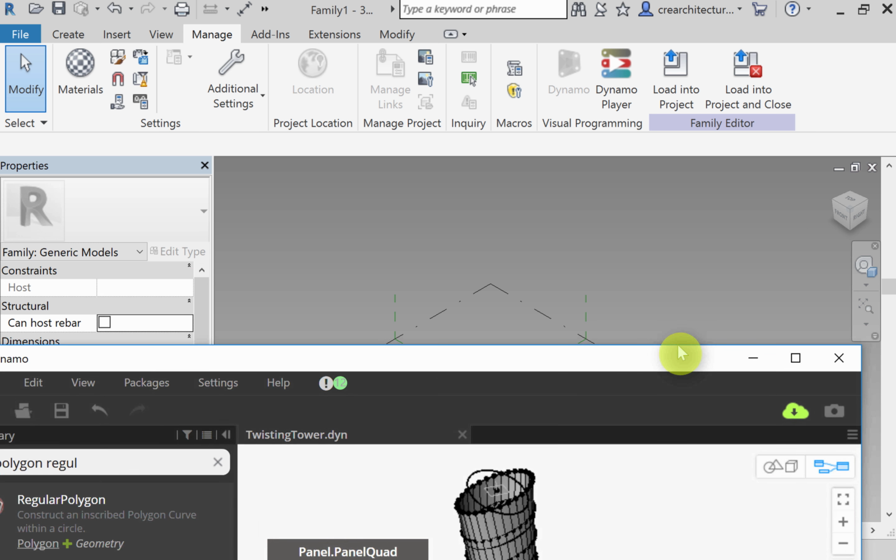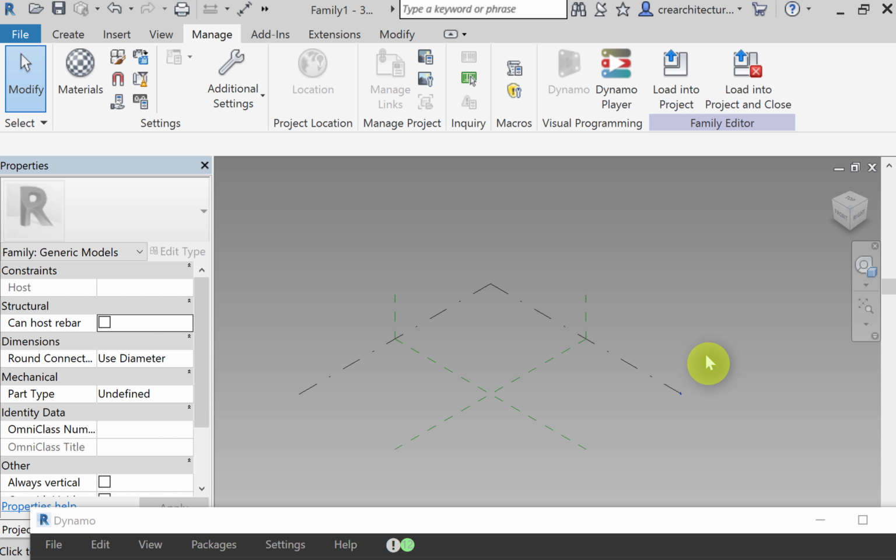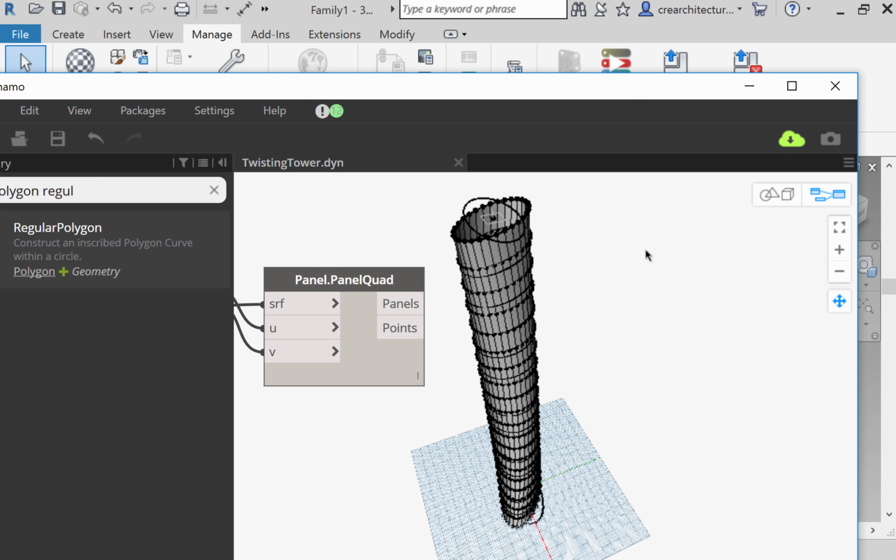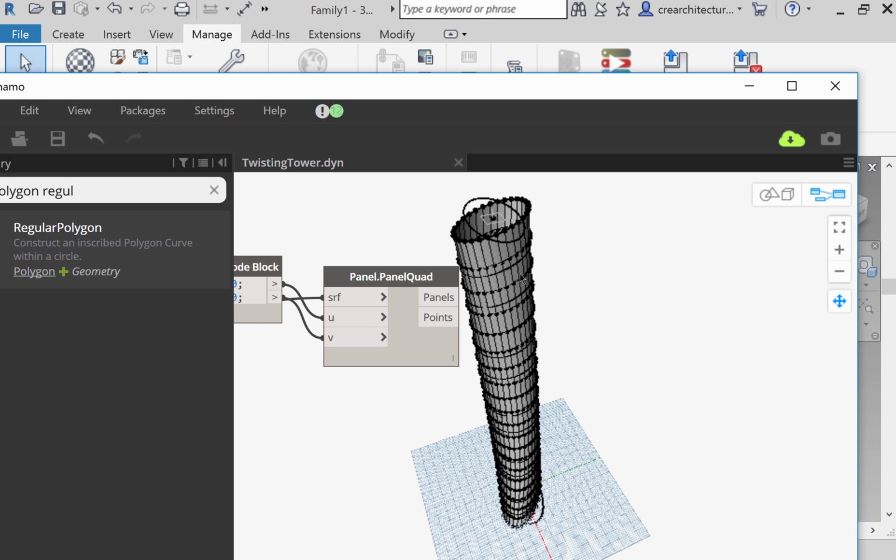All right, so I'm going to leave this a little bit on the side, and now I'm going to focus. You see, nothing is going to happen in Revit until I bake this with an adaptive component. Oh, let's do something. Let's do the floors. We have the contours for the slabs, but they are actually at the surface, right? Maybe we need to scale this by a little bit so that they are inside the surface and they don't overlap the Revit geometry.